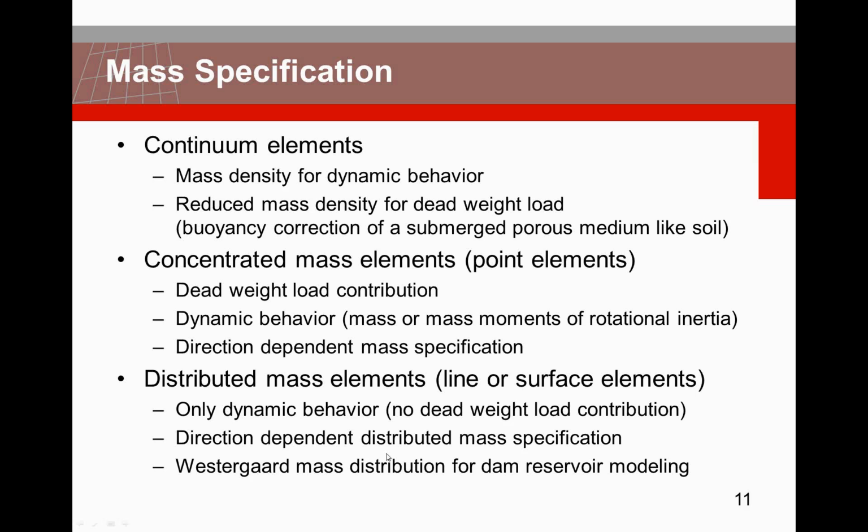So without doing a full fluid structure interaction, you can still account for the mass of the reservoir by applying distributed mass elements. Alternatively, as we will see later, you can do a full fluid structure interaction to calculate the mass distribution.